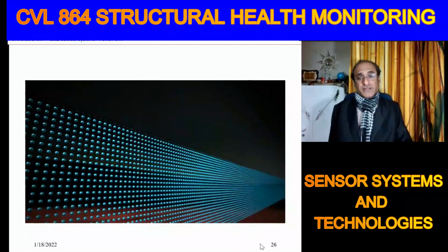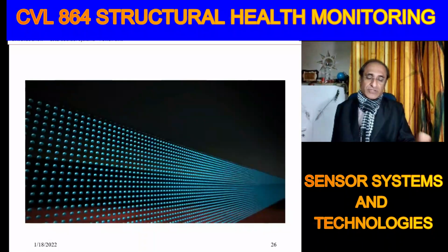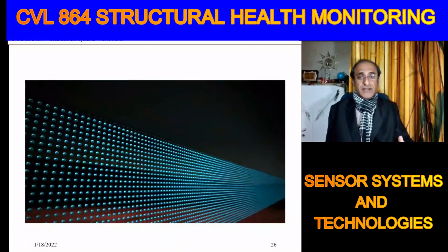So this is the illustration of one application of the piezoelectric materials. In piezoelectric materials, when we apply an electrical field, they will undergo expansion or contraction. You reverse it, so whatever was expanding will undergo contraction, and vice versa. What they have displayed here is that if you bond a normal metallic plate with a piezo, application of this kind of potential difference or electric field will lead to bending, and that's what is used in inkjet printers.